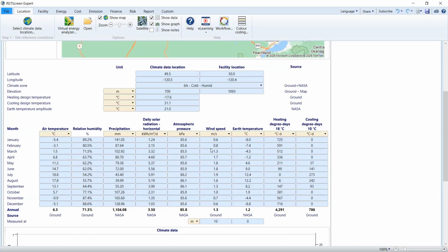Why? Because the kinetic energy of the wind that's available in the wind is a linear function of its mass, right? And what do we mean by mass? We mean the density of the air. And the density is determined by the atmospheric pressure. That is how much the air above our location is pressing down on us, and the air temperature. That is how cold it is.